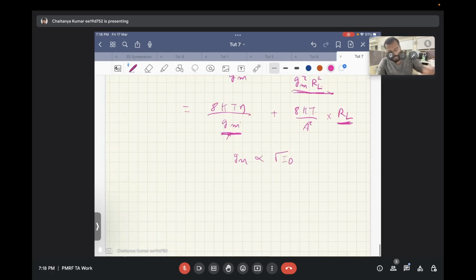So, see, full swing voltage depends on. So you will first do dynamic range scaling. Dynamic range scaling will help you achieve maximum signal power that is possible at each node, right? Yes, sir.